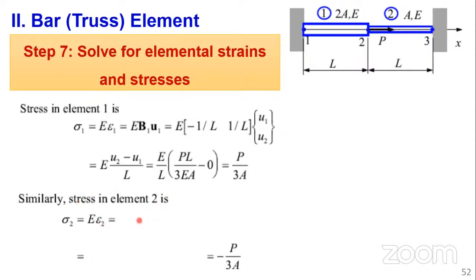Of course, I know in your notes you have them, but it's good to work it out and see whether you can obtain it. And as you can see, stress in bar 1 is the same as stress in bar 2, but of course, different in nature. This one is tension, of course. This one is in compression.